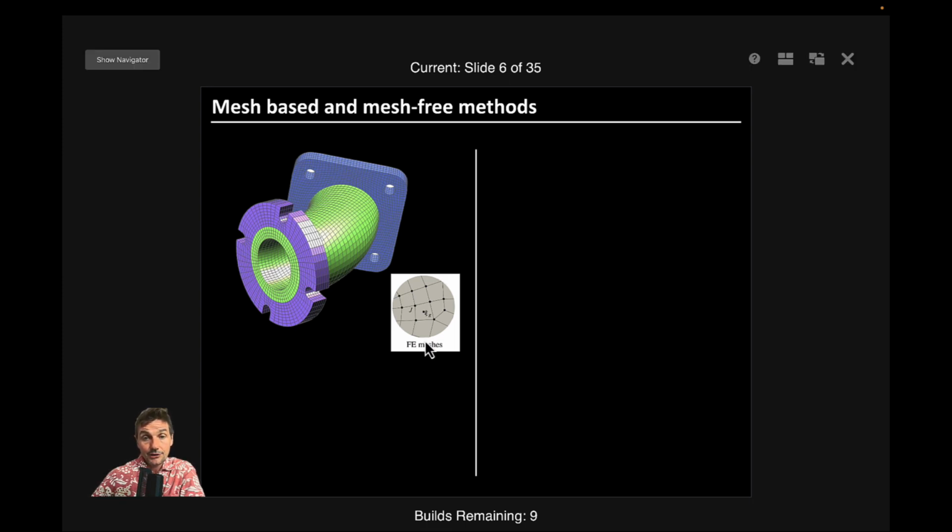So, okay, what is a mesh, basically? That's the question. A mesh does many things, and that's why when people talk about mesh-free methods, it is so ill-defined, because a mesh has many, many roles. The first role is to build the approximation. You see here, you have these little nodes, J, and a point, psi G. And what happens with that? Well, the nodes that you have here are used to build an approximation scheme. So they are used to build what are called shape functions.